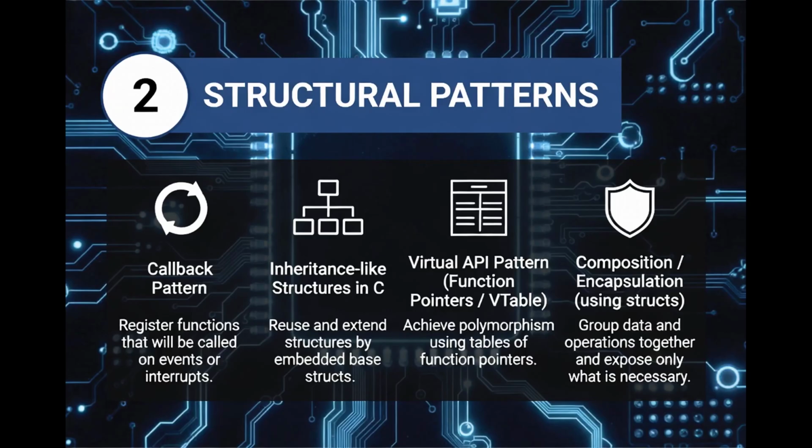When an event occurs, the firmware invokes the callback. This is the foundation for interrupts, DMA completions, network packet reception, timers, event-driven systems, etc. Callbacks reduce CPU wastage, improve responsiveness, and enable highly modular architectures.